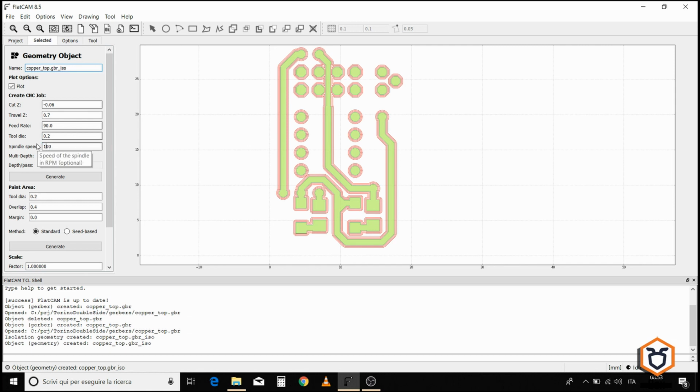The spindle speed in this kind of machining has always to be the maximum. Remember that the spindle speed is really important, since a higher spindle rotation speed will result in more defined traces. Clearly, using the spindle that we suggest, the rotation speed will be around 5000 rpm, and using a 3 cutting edges bit, the effective rotation speed will be about 50,000 rpm, that is a good speed for this kind of machining.